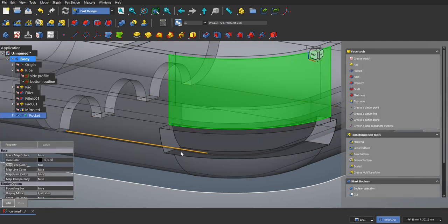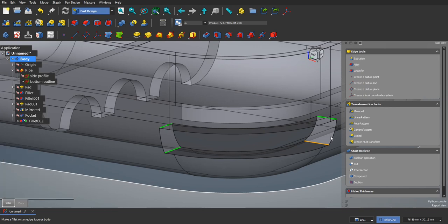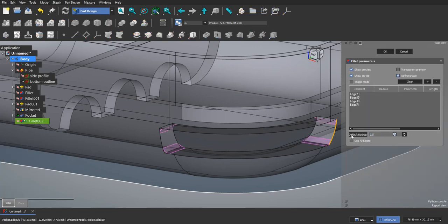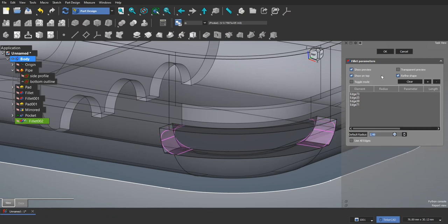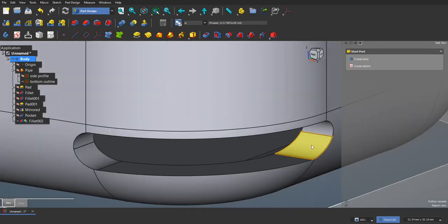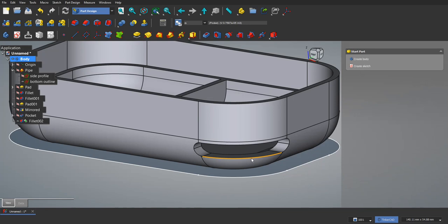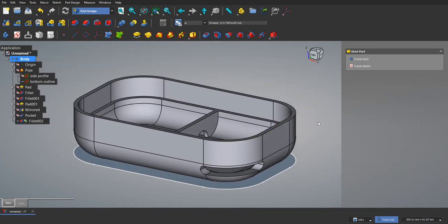So I will click on any other face, and that will turn it into wireframe mode. So fillet there. See, if I type in 2.5, recompute failed. However, if I do 2.49, that's pretty much what we want, and it worked just fine. Works like a charm. It's a bit cheesy, but that's just sometimes what you have to do in FreeCAD.